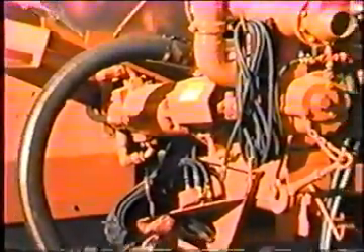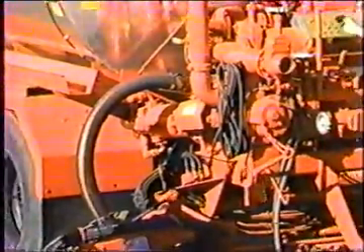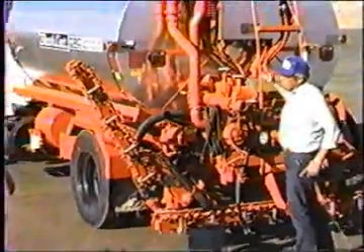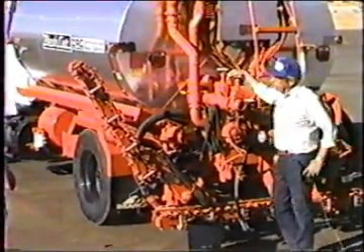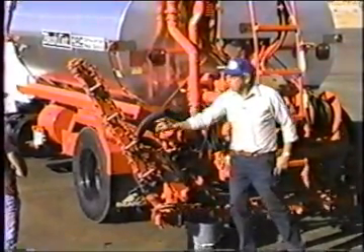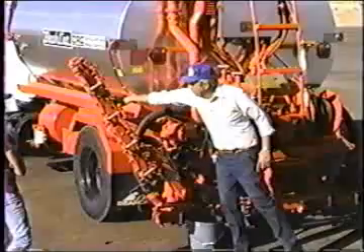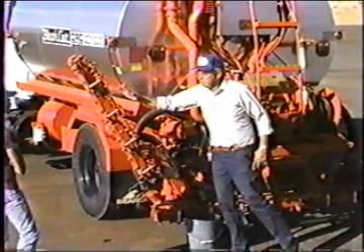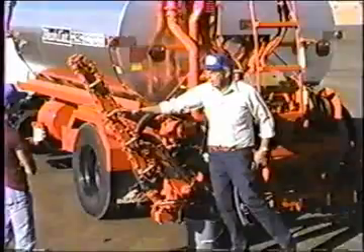And the reason for that, when that wing is in the up position, let's say that we put the wing right there or even clear up, the weight of the wing is trying to push it down. Okay, so it's initiating flow at the hydraulic cylinder. It's trying to push fluid out of the cylinder to let the wing down.